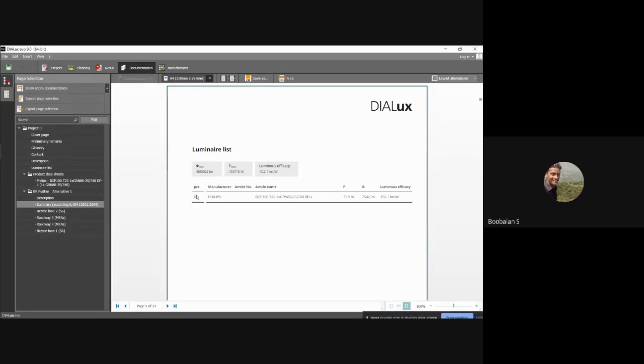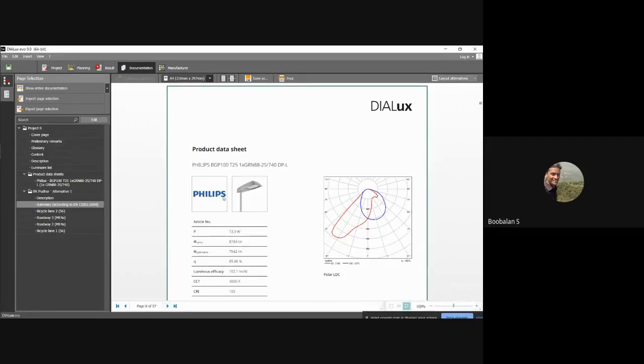We had given it. Total 61 lamps are used, and totally around this much lumens for a single lamp. Luminous efficiency is 100 lumens per watt. And this is the lamp which we have selected, so its technical specifications and then description.